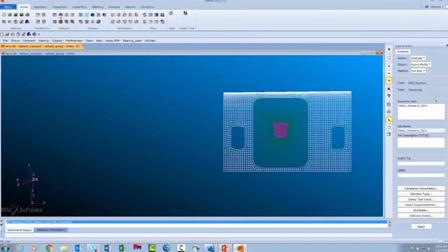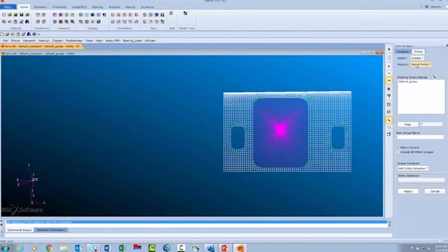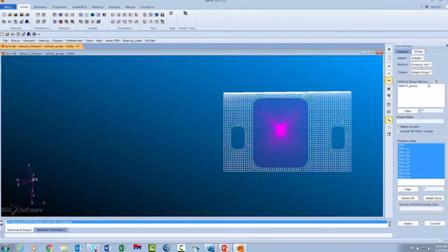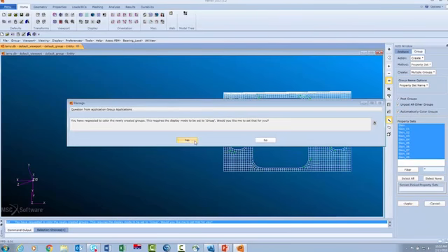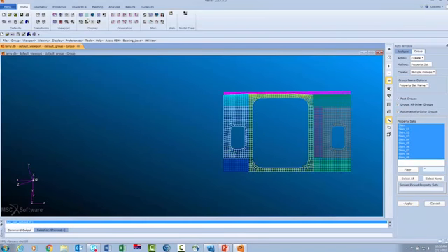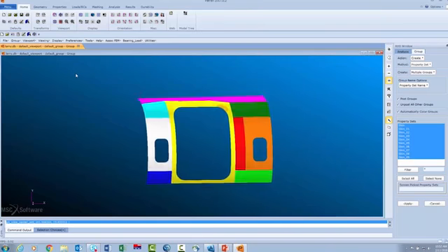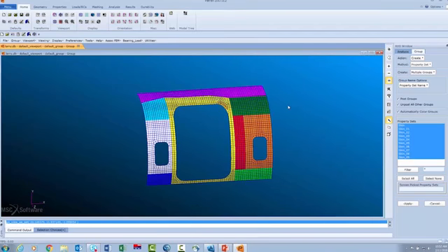And let's go in and let's actually create some groups. So we'll create groups based on our property sets, okay? Have a bunch of those. Let's post them, unpost, and color. And what we'll see here is we'll see colors in the model where the zones were. So I can see all of my zones that I had. So we've exported the PCOMPGs. We've got all that information ready if you wanted to do something else with this model, especially if you wanted to run it in Nastran, okay?